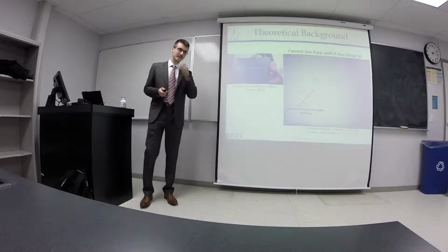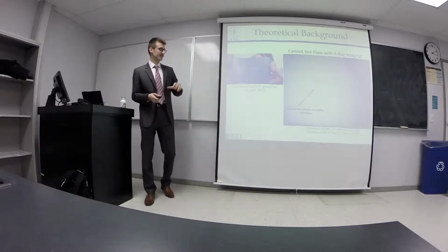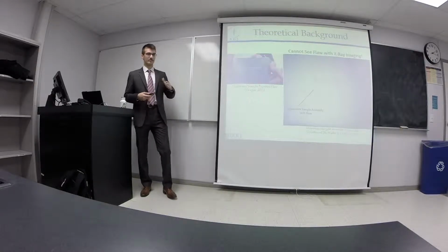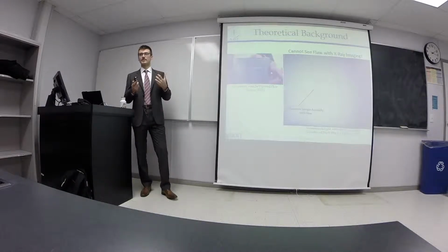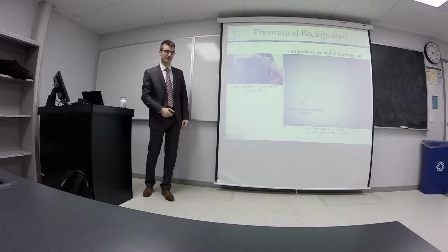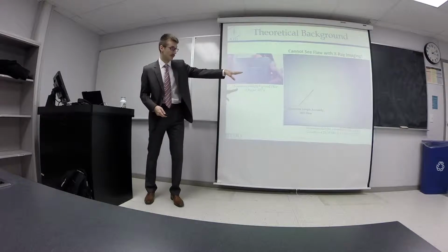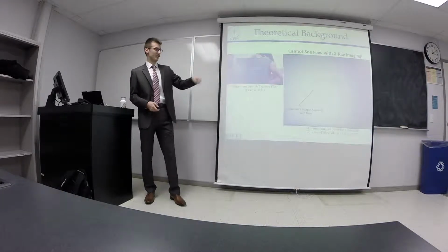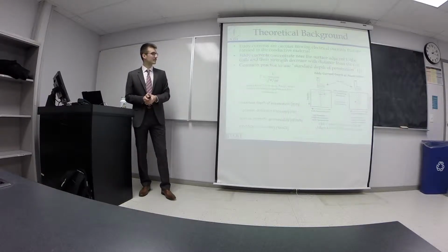Why eddy current is chosen. You can see the sample on the left is the example of aluminum that I was playing with for this design. Some of these cracks you're not able to detect with other conventional methods like X-ray imaging. On the right there you can see, using the UA X-ray imager we have, I wasn't able to see the crack at all with any of the images that were produced. So it has some advantages when compared to other methods.